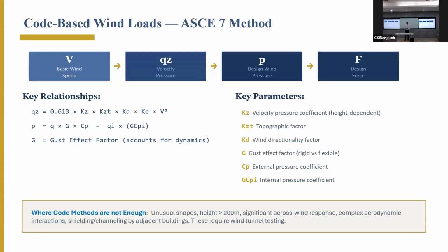Normally it takes a lot of time and effort to do these calculations, especially for a low-rise small building like a warehouse or a pitched roof house. Very complicated because of the angles and the directions of the roof. The whole thing becomes very complicated. It takes hours and hours just to calculate wind pressures. Now in a building, ETABS can do that automatically because it knows the building size, but then you have to define a diaphragm so it can calculate the size of the building at each floor. So it tries to do those things automatically.